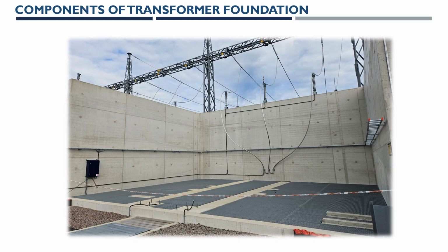Also this precast concrete element is holding the cable ladder which is running all around. So the conductor, the dropper, is also fixed here for earthing purpose on the transformer firewall, and its control box is also fixed on the transformer firewall.